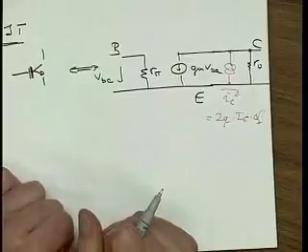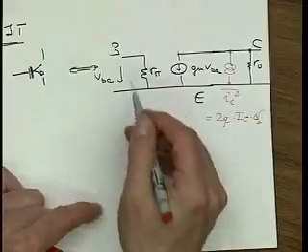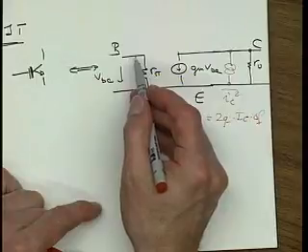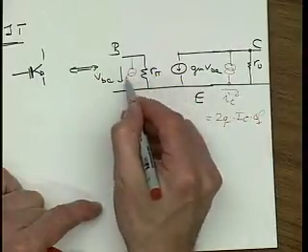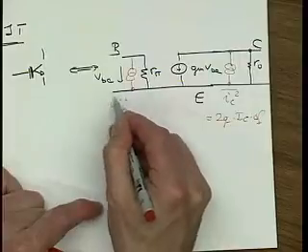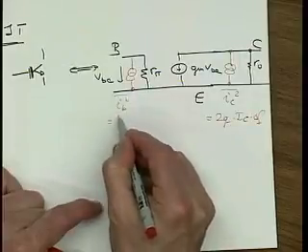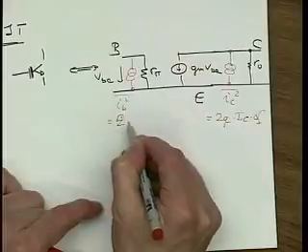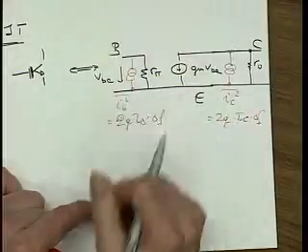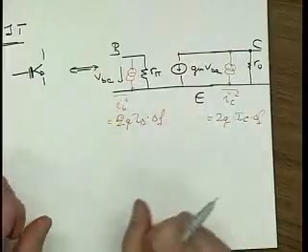And then there is also a diode between the base and the emitter, and we're going to get more shot noise there. That's IB squared, and its value is 2q IB times delta f. These equations are also written on the handout.